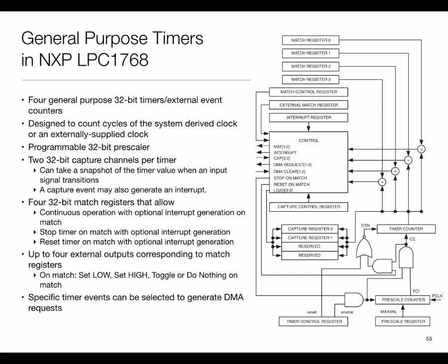They are actually also used in the reverse direction. Many sensors send their values in a pulse width modulated waveform. So it's very common, for example, for motors to tell their position or speed using a pulse width modulated signal. PWM signals are nice in the sense that they have digital values, 0 and 1. The value is binary, but the analog value is carried in the timing of the signal.